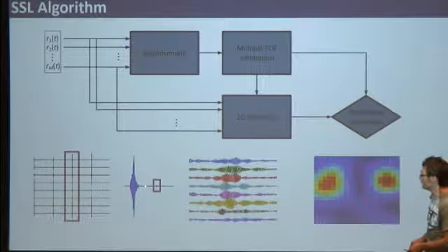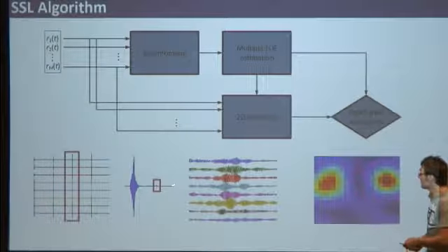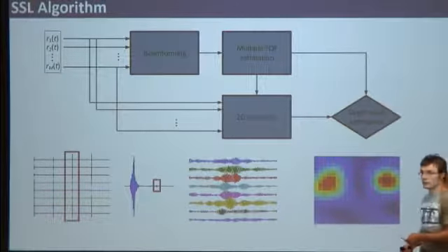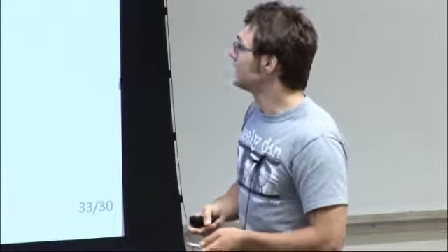And in this output, I find peaks. Here I find one peak. But actually, I find several peaks every time. Okay, I find, for example, the largest 3 peaks. Now what I do is I zoom in to this peak and go back to raw signals, and feed these raw signals into the source localizer. And then I try to see if the direction that this reflection is coming from agrees with where I think I'm looking. I do this for many peaks inside every beamformed signal.